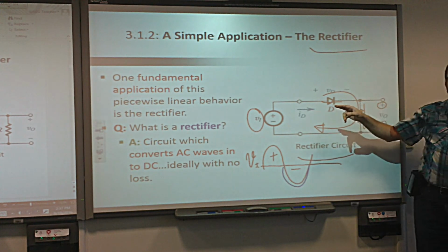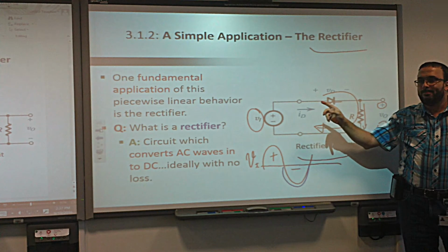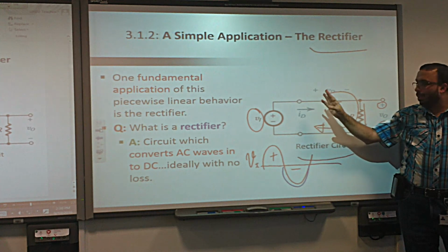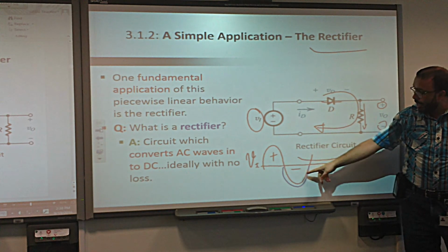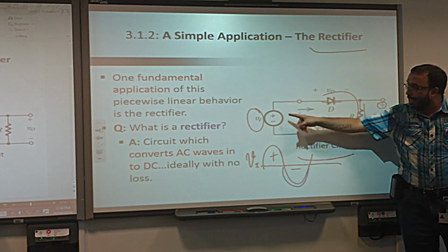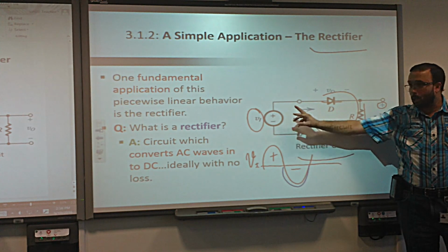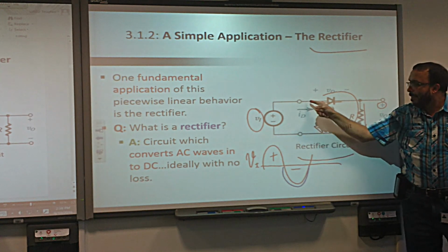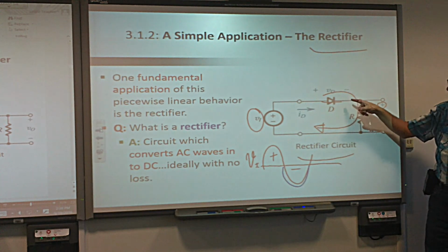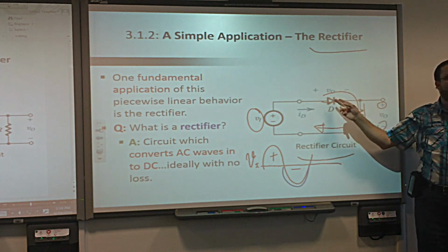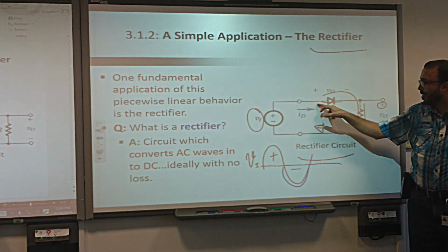Very good. Why? Because it goes from low voltage to high. But hold on a second. If it is now in the negative, that means this voltage here is less than this. It's opposite to the conversion here, okay? So this level, less than this, that means this is bigger than this. So in this case, it's open circuit.